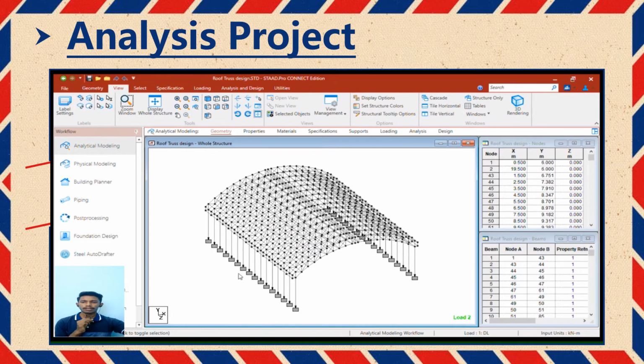Hi and very good morning. Okay, as you can see, this is the design for our roof truss for the building. As for the dimensions of this roof truss, the span of this truss is equal to 24 meters, the length is 19 meters, and the height is 9.5 meters. As for the height of the column, it is 5 meters from the ground to the end, and the height of the arc is 4.5 meters. The spacing between each truss is 1.5 meters.